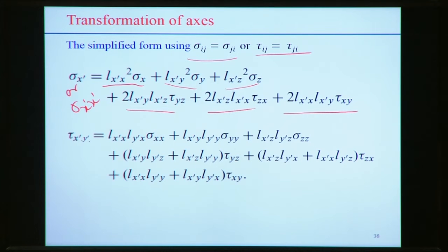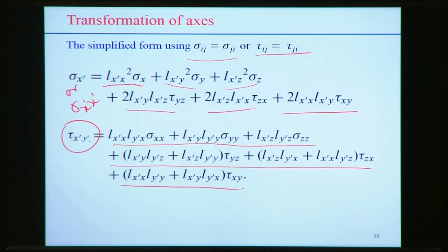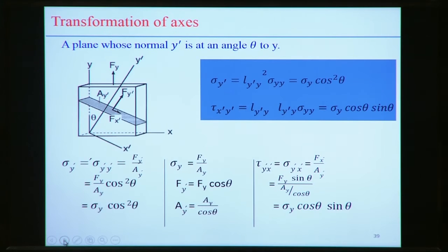Similarly, when you try to represent the shear stress, we can further simplify the expression by looking into the direction cosines and the different stress component values. We can define the shear stress value in the new set of axis system. So this transformation of the stress from one axis system to another axis system can be found using this simple formula.